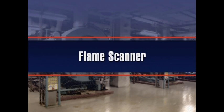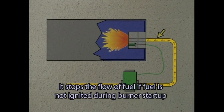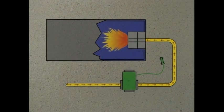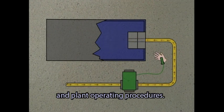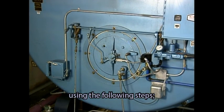Flame scanner. The flame scanner verifies or proves flame in the burner. It stops the flow of fuel if fuel is not ignited during burner startup or if a flame failure occurs. Flame scanner testing frequency will depend on local requirements and plant operating procedures. The flame scanner is commonly tested for proper operation using the following steps.